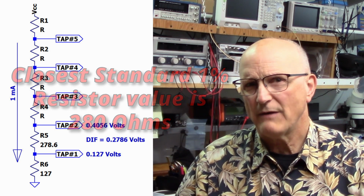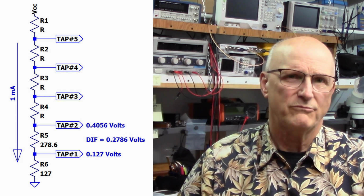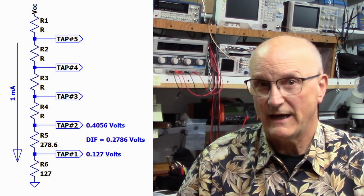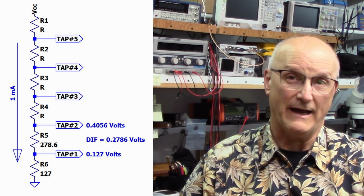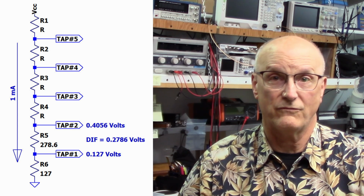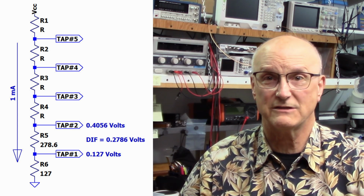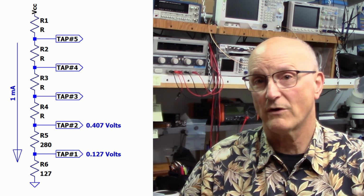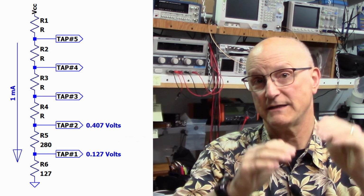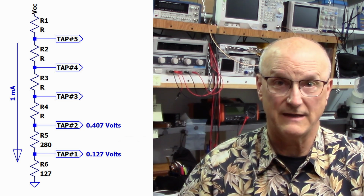The voltage drop across this resistor will be 0.280 volts. So the actual voltage at tap 2 is the actual voltage at tap 1 plus this 0.280 volts drop across this resistor, which gives us 0.407 volts, which is within 0.35% of our target value. Now, I'm not going to go through all the rest of the taps. We just continue this same process tap by tap for the next 3 taps.